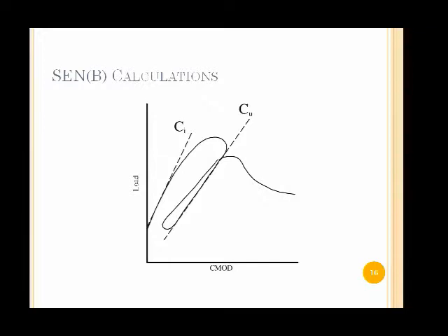The first 50% of that initial loading is what we're going to call our initial compliance. And then we load until we get to a peak load, and then we unload it in a controlled manner. So this test requires a closed loop hydraulic system usually. And from this unloading curve, we get the unloading compliance. And then we can reload the specimen to failure so we can get a total fracture energy. However, to calculate K1 or K1C, we only need these loading and unloading compliances. The rest of the curve is not important.